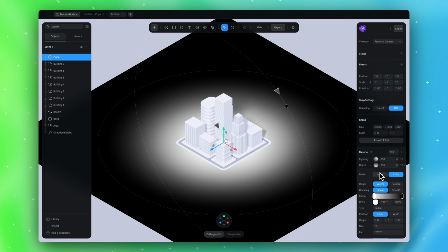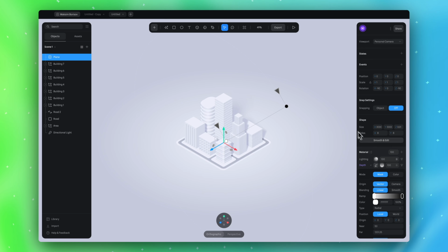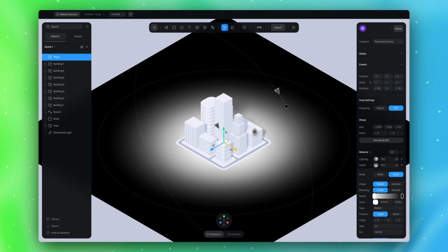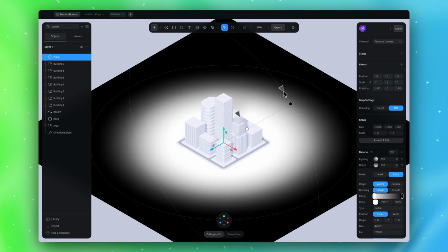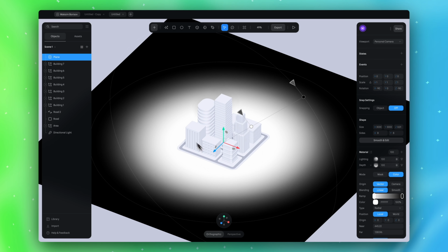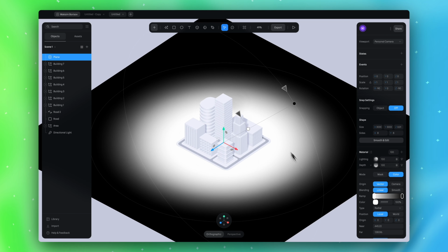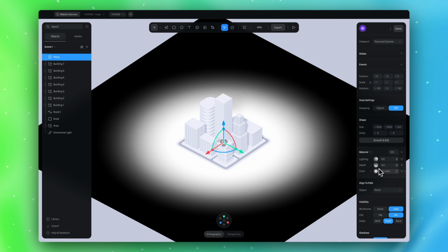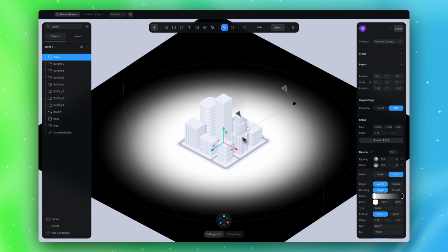And then I select mask. So what I did, I said that this depth material with this map where we have white in the center and black around, I want to apply this as a mask, which means show me the material which is behind, at the bottom of the mask, where I have the white part, and don't show me where I have the black part.